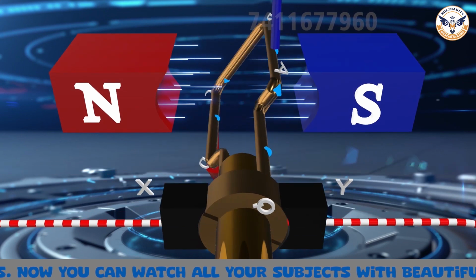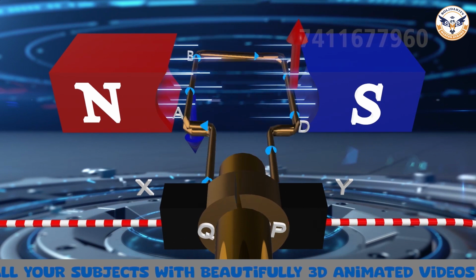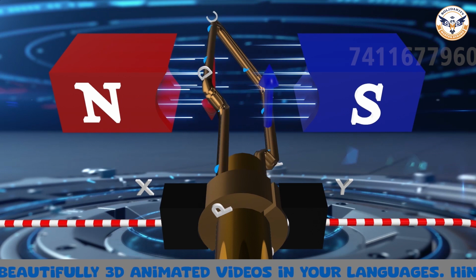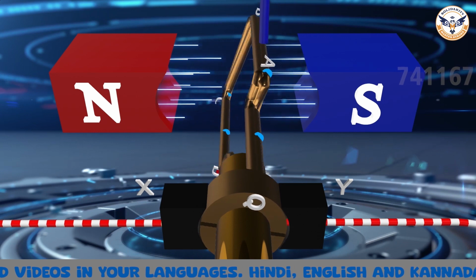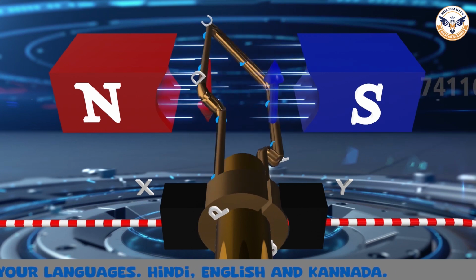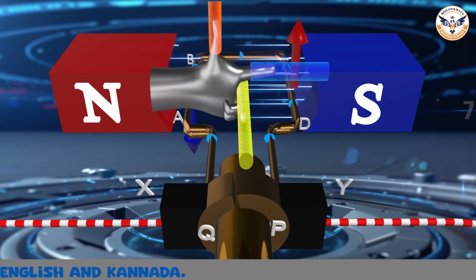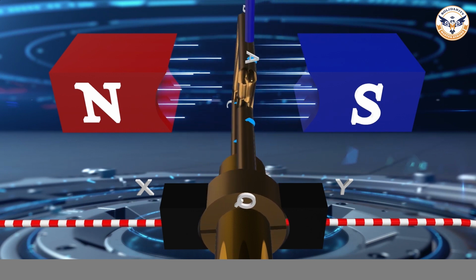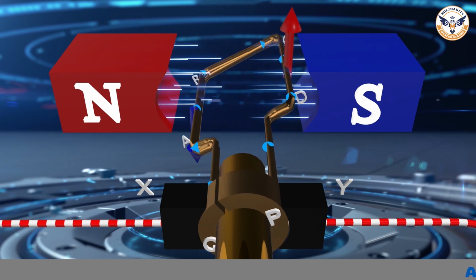The reversal of current also reverses the direction of force acting on the two arms AB and CD. Thus the arm AB of the coil, that was earlier pushed down, is now pushed up, and the arm CD, previously pushed up, is now pushed down. You can again verify it using Fleming's left-hand rule.